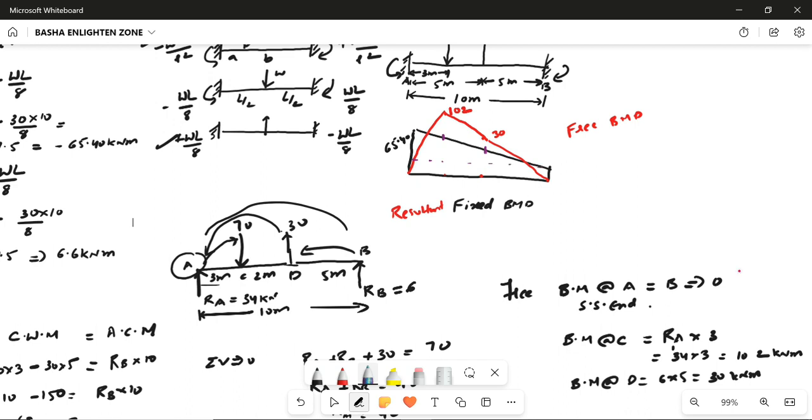First we know up to here the entire rectangular span will be 6. So the remaining part will be based on the two symmetric triangles. The remaining span distance will be around 7 meters, I think. So for the total span length how much you will get, and for the small length of 7 meters how much you will get. Like in the previous example 3, I found this net bending moment value based on these two similar triangles calculations.